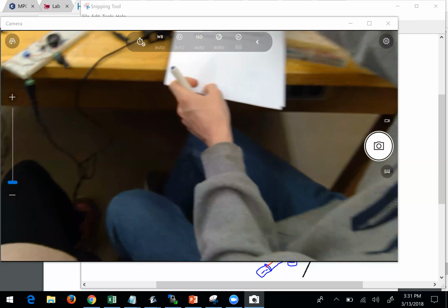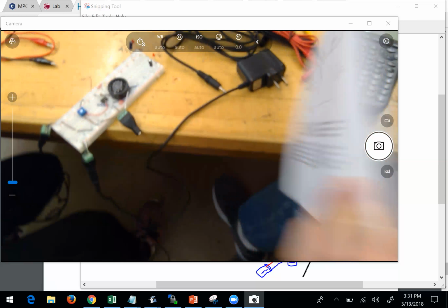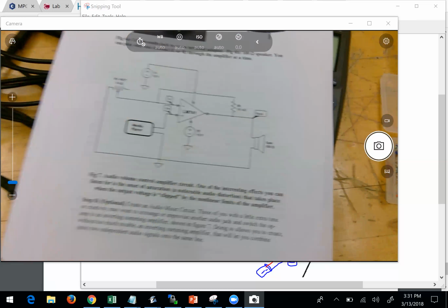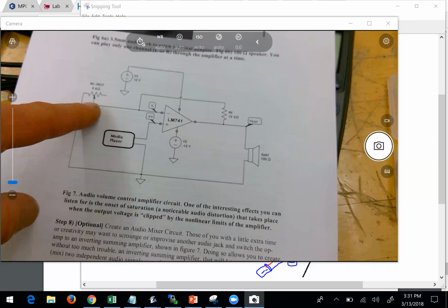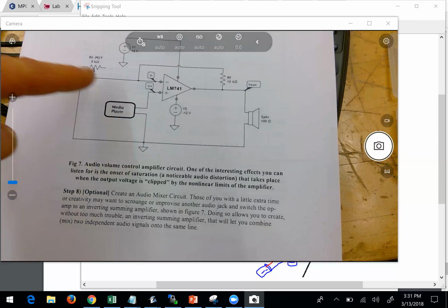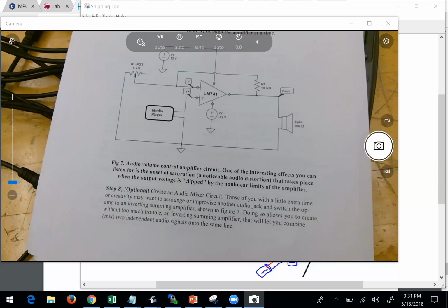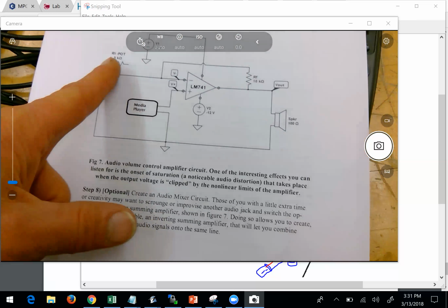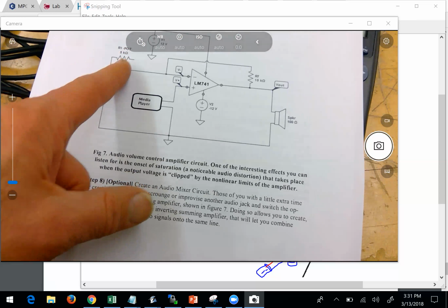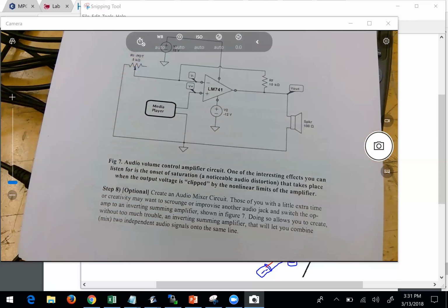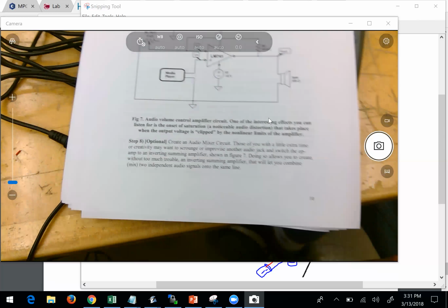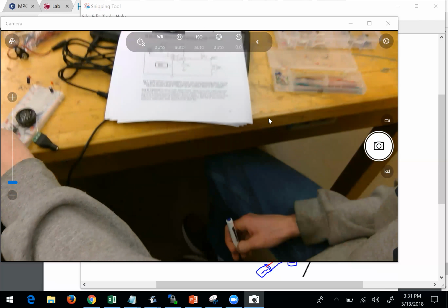We're doing the sound one. Good. And we're confused on how to wire up the potentiometer. Well, a potentiometer has 3 wires, and you only need to connect between the middle and one of the sides. Really? Yeah, because then you have a variable resistor. As you turn it, you're going to pull in more and more of the resistor on the left, so that can go from 0 to 5K. Oh. Yeah. Okay. So we don't even need this wire.